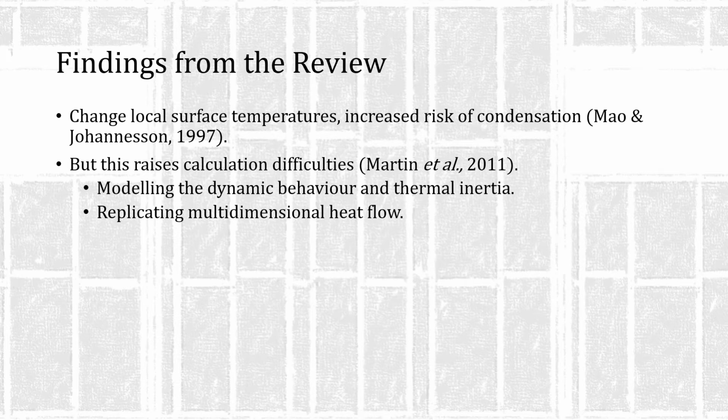Martin et al. identify two factors that increase the complexity of a tool and improve the tool's ability to replicate the behavior of thermal bridges. The first relates to modeling the thermal inertia of a thermally bridged building element and the material's ability to store heat. The second relates to replicating 2D and 3D heat flow that occurs due to thermal bridges.